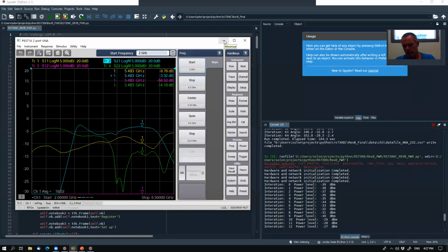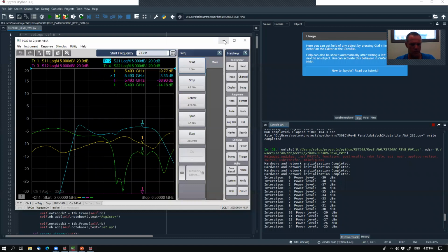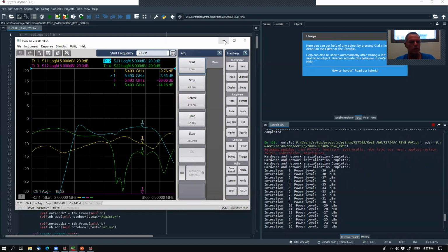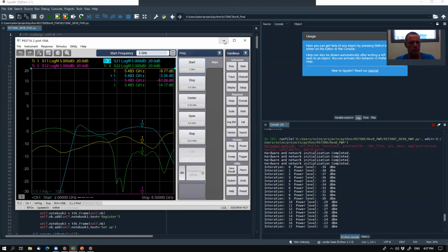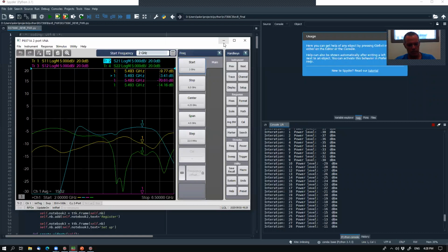It's important that we have a network analyzer, and there was a difference from the old network analyzers to the new one. Many of the old ones have a sweep range from -20 to 0. But actually, when it goes above -10, the amplitude and phase starts to change. So you need to make sure that you have, for this type of measurement, especially if you want to characterize AM to AM, AM to PM, a network analyzer that preserves the phase across the sweep. Otherwise, you're going to have to calibrate that phase as well.